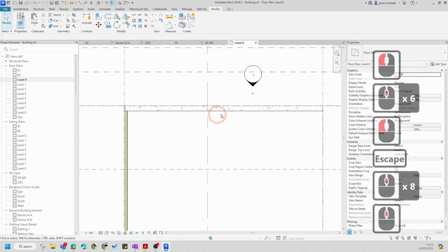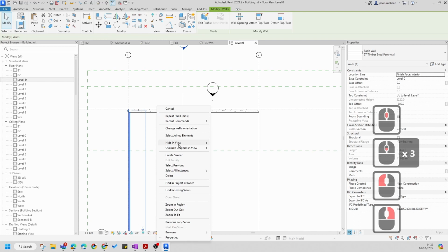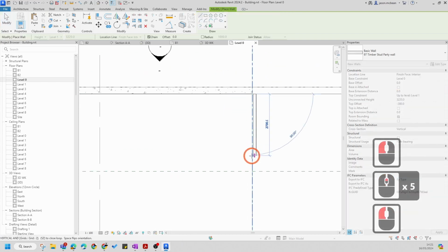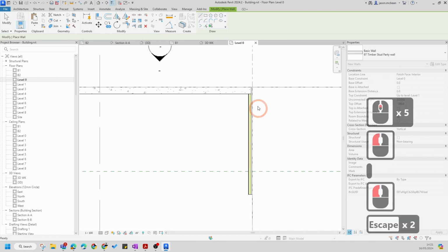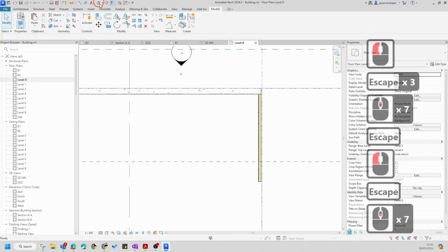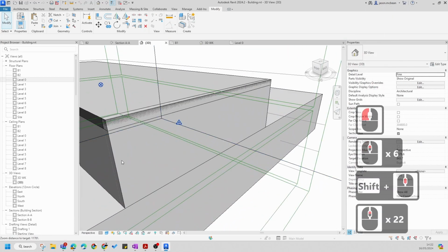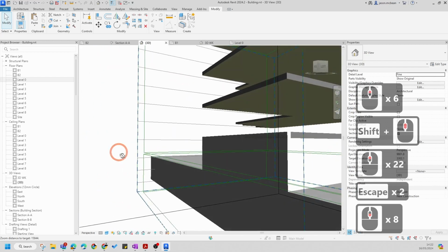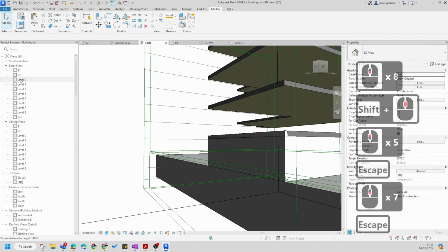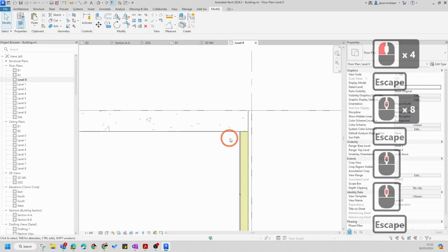Grab this wall, create similar. Remember, face interior, and then you press spacebar to work on the other side. So technically I've got a party wall there and a party wall there. What is interesting, from the exterior, you're not going to see that thermal gap. You're not going to see that thermal layer because it makes it read as a layer. So it's just one of those weird situations.